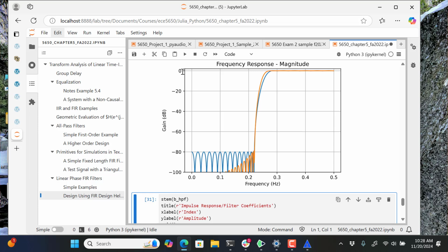so now you can see why the Kaiser window takes more taps. With the equal ripple, we're just saying, just give us an equal ripple level, more efficient. Here, we're meeting that requirement, right in this neighborhood, but then it continues to go down. So we're getting maybe more bang for our buck. Well, we're getting more bang than what we need. It's a trade-off, though, and I wouldn't say one's right or wrong. It's just the way it works out.